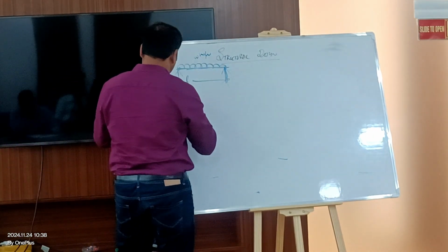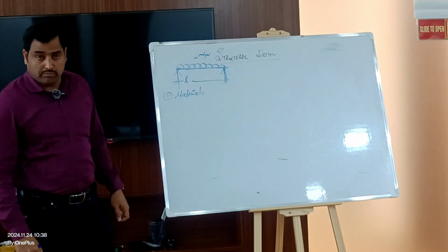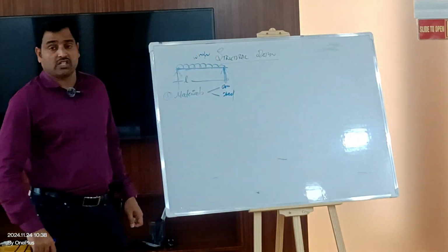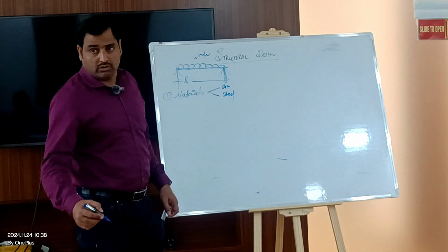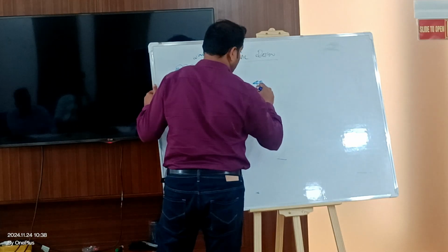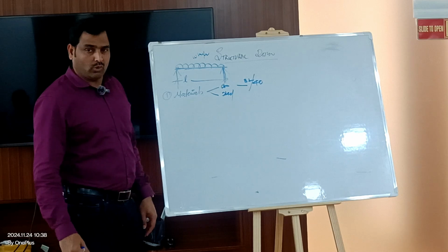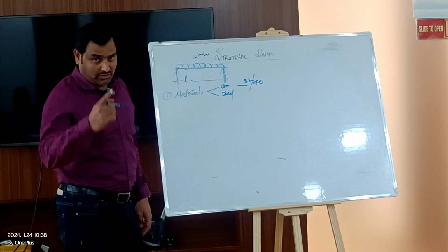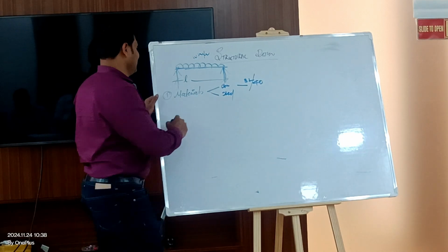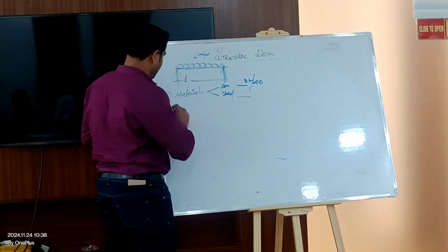Okay. The first one is what? Materials, right? The materials, concrete and steel. Fantastic. What is the minimum grade of concrete? 30 actually. 30 to 40. 40 is cubical or cylindrical? Cubical. Then cylindrical will be? 32. 30. What is the correlation? 0.8. Whatever it is, 20% or 80%. Like he said, actually 1.25. Okay. Grade of steel? 460, 500, 550, whatever is there in the market, you can use it. It doesn't matter actually.